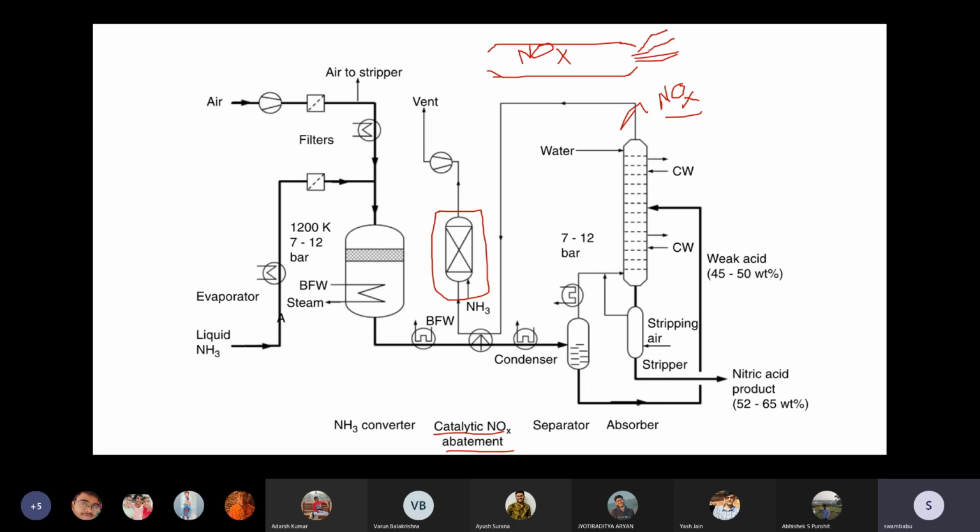That's why nowadays government regulations enforce that every vehicle, every 6 months, has to go through this testing, although nobody cares. Because this converter tends to get deactivated with time, it needs reactivation. So whether everything is going okay or not, they have these emission measurements for every vehicle every 6 months. We need to get a certificate showing the concentration of exhaust coming out.